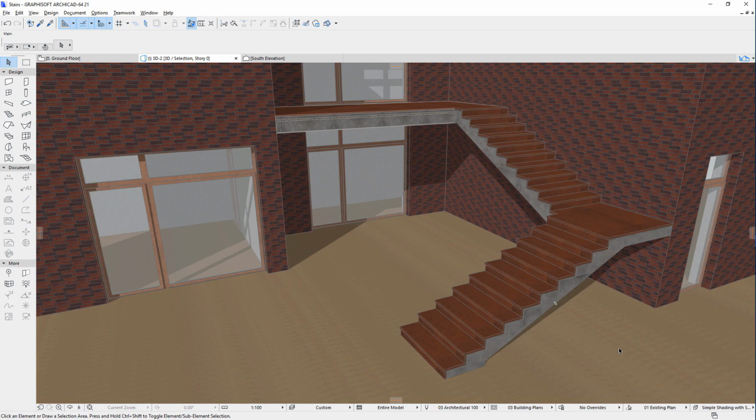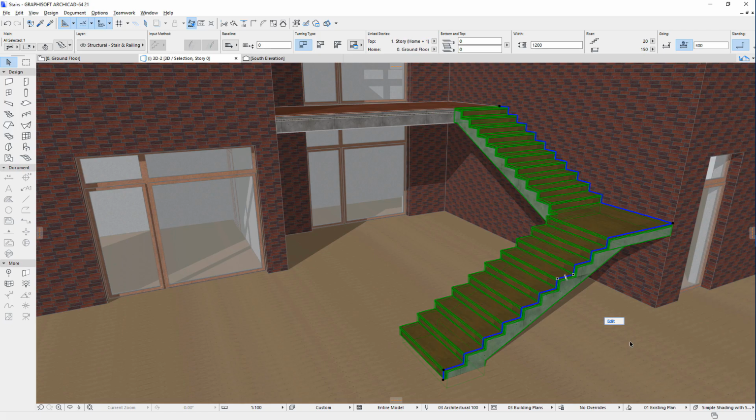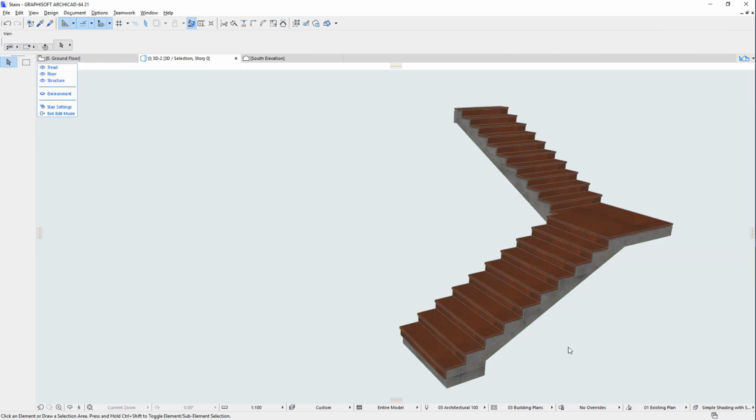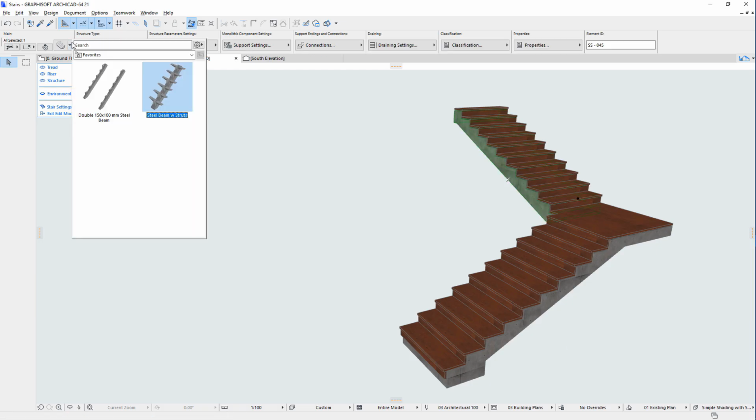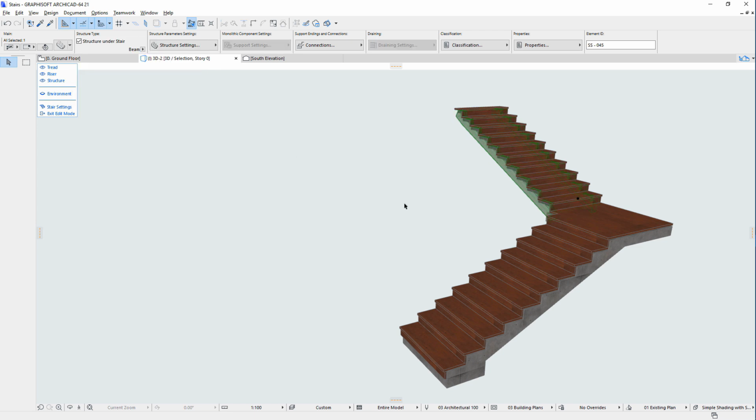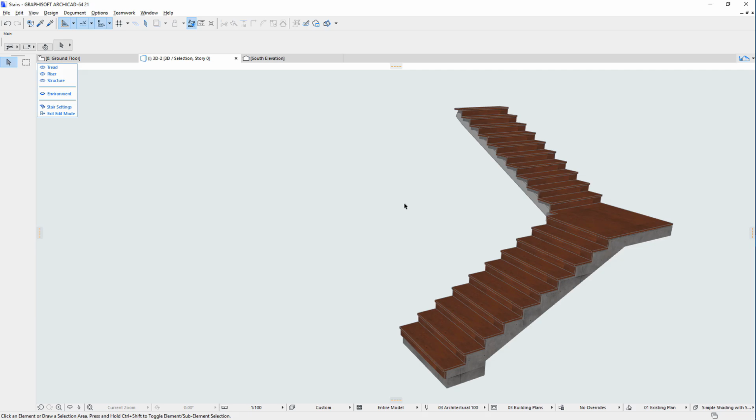The structure of stairs may also be customized. In a stair with multiple flights or landings, all flights or landings will have the same structure. However, in edit mode, you can select any individual flight and change it to a different structure with different parameters, or modify the parameters of its current structure. The same is true for landings. Select any individual landing and modify its structure and its parameters to any desired value.